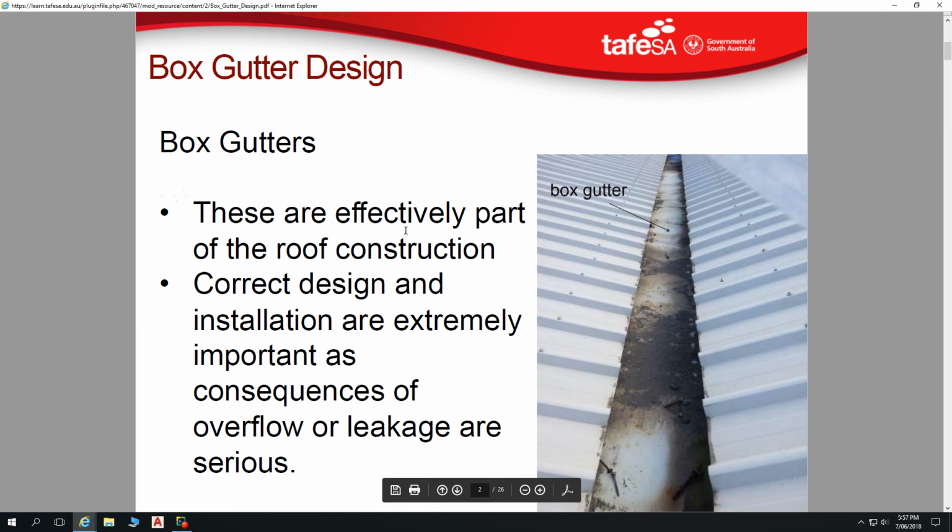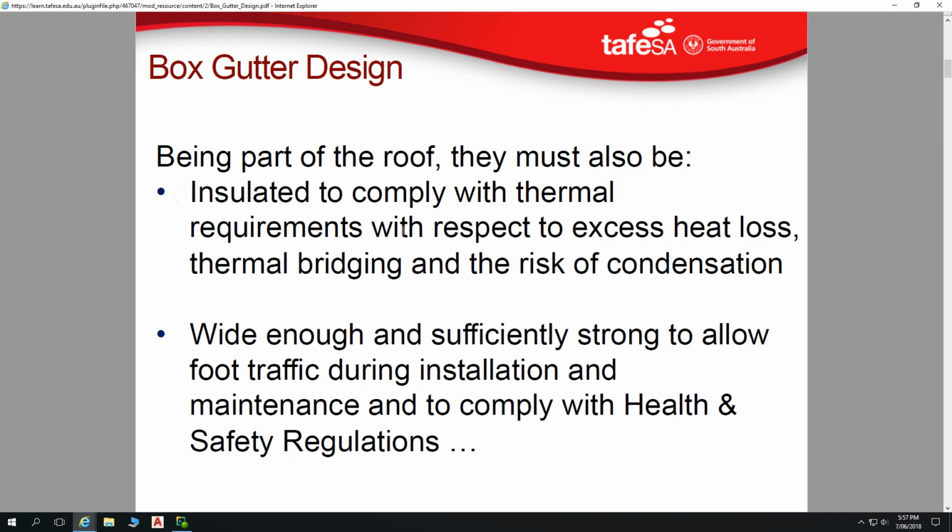But correct design and installation of box gutters is extremely important, because when box gutters overflow, they don't overflow anywhere but inside the building or inside a roof cavity, and that's why they get poo-pooed a bit. But they do make various different architectural solutions possible. Also, with box gutters, it's good to design several outlets. So if one outlet gets blocked by a plastic bag, for example, water can rise up and then go out another area until that obstruction is cleared.